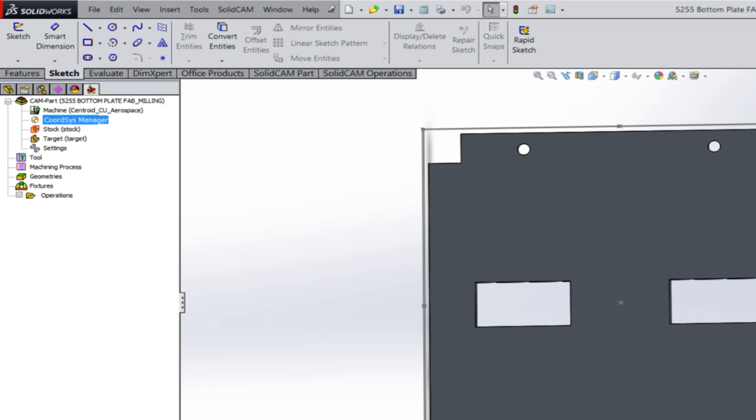Now, in the case where you're not bandsawing a piece out, let's say this piece existed already, a machinist cut it and made it nice and smooth edges here, but he forgot to put the holes in, or he forgot to put the pockets in. In that case, this edge is already machined and accurate. So you need to put dowel pins here or here to align this piece perfectly with the movement of the table travel, either in X or in Y.